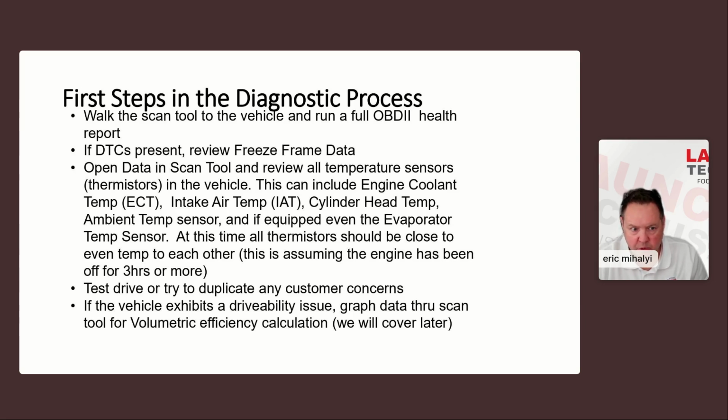Well, I mean, I don't know. Did we somehow get transported to Neptune? Because how's it minus 88? I'm wearing shorts right now. That's impossible. So, people are turning on their AC, or they're doing this, or evaporator temperature sensor, same situation, requesting 60 degrees, which in most cars is like low temp, and then their AC doesn't come on.